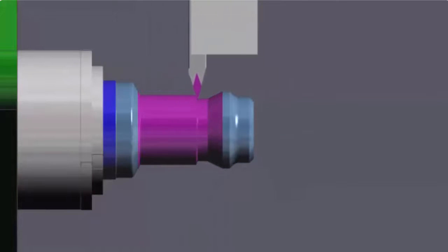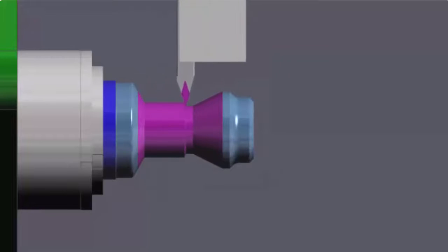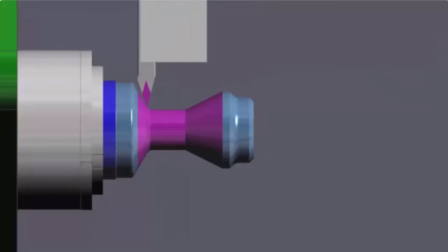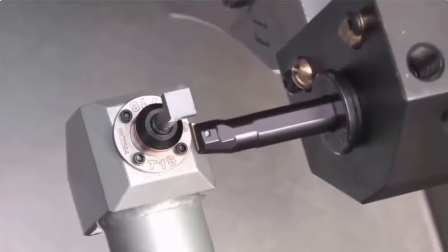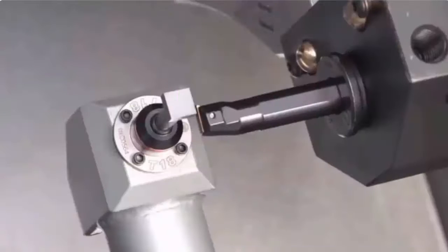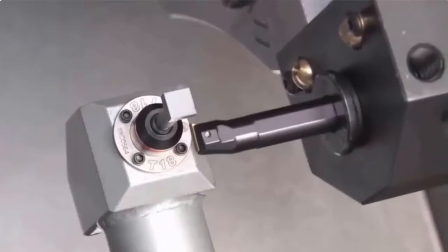And this can be really important, or it definitely is really important if you're using cutter compensation, or if you use a tool presetter, a device for checking the tool automatically, then the machine will want to know what type of tool you're using, and that's how it knows which side of the setting arm to set the tool to. So it's going to approach that setting arm in a different way, obviously for a different tool.